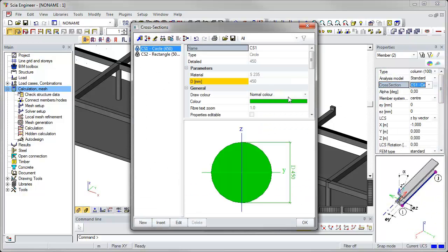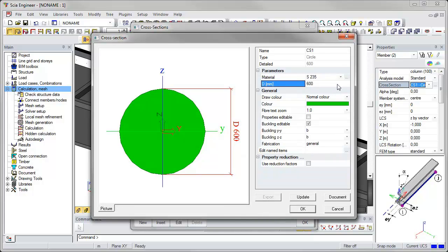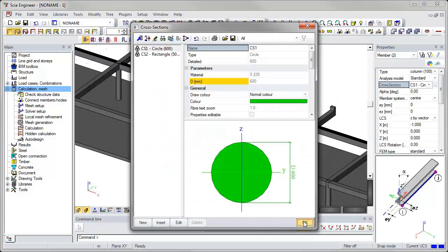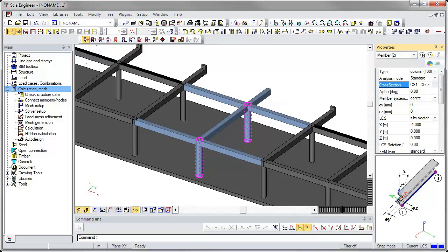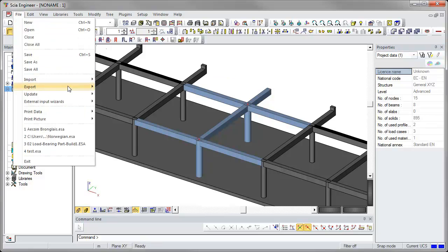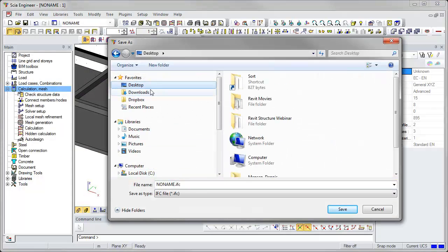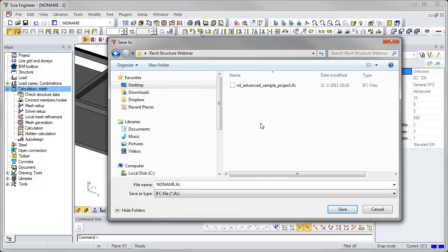Of course, we can adjust the model according to the results and the building codes, but instead of sending it back to IFC, back to Revit Structure directly, we use tools such as Solibri Model Checker to analyze changes that have been made. According to the results in Solibri Model Checker, we report to the modeler and he will correct the Revit Structure model with the changes made by the engineer. Although this might seem extra work, it makes it clearer who is responsible for what, and it highly reduces the possibility of errors.